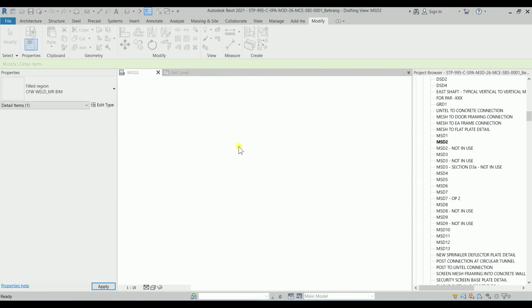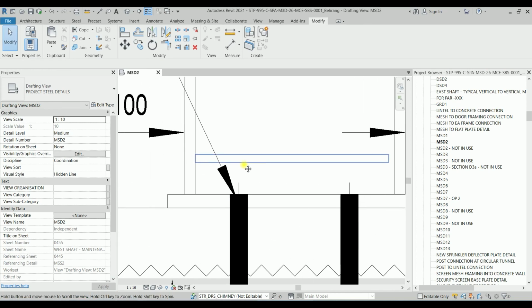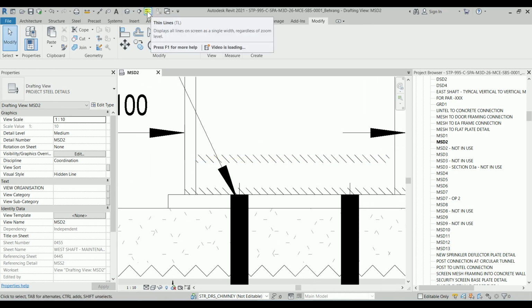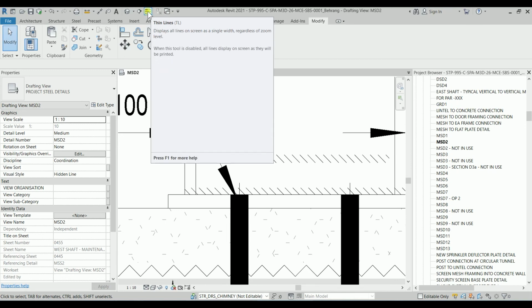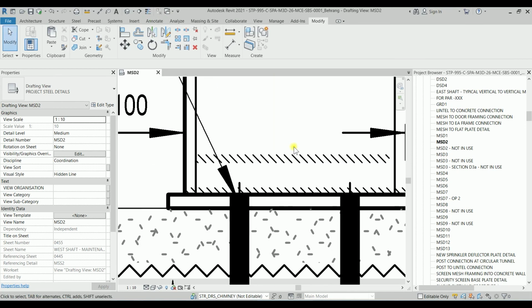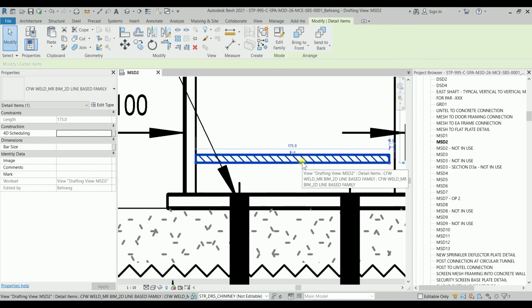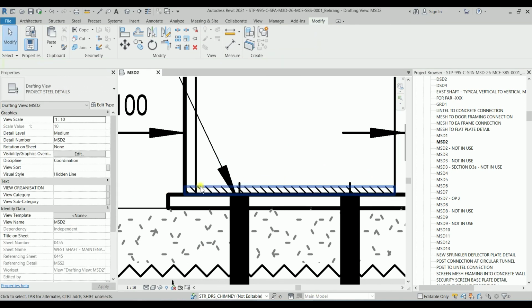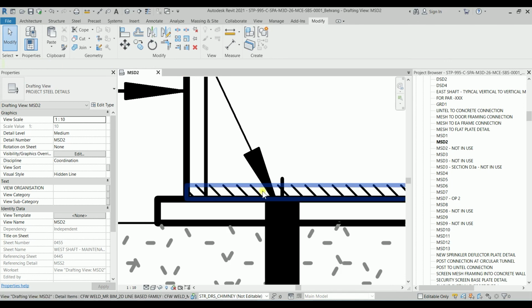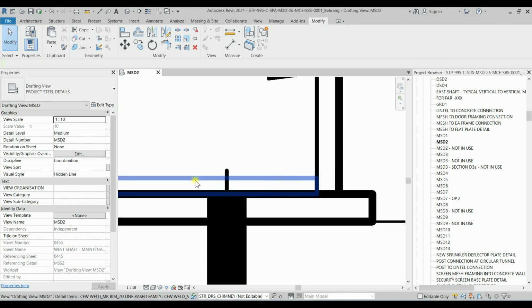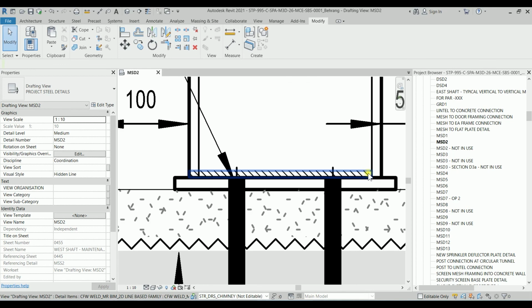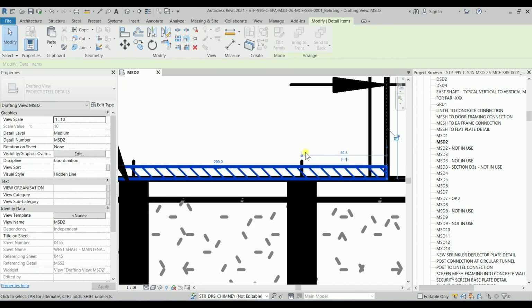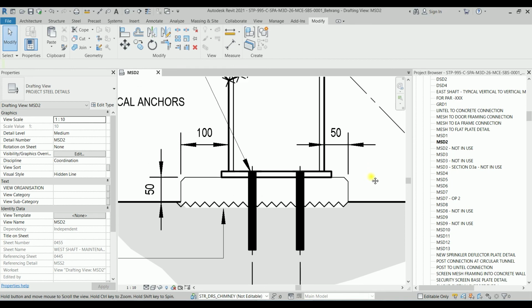Let's override it. As you can see, the spacing is 5mm. I'm going to switch off the thin lines, and delete this one. I'm going to select this one, type CS for creating similar, and we have a new family for our weld. So now the line is not sticking out. If you want to change its color, you can do it, and it's a much cleaner family. It should be up to here, so it's clean and neat.